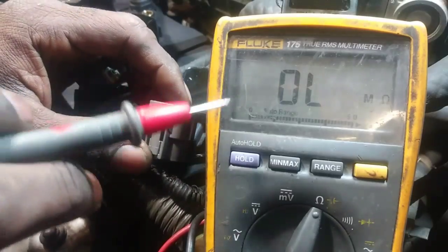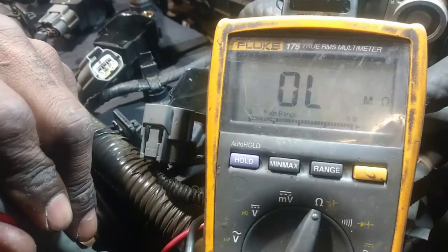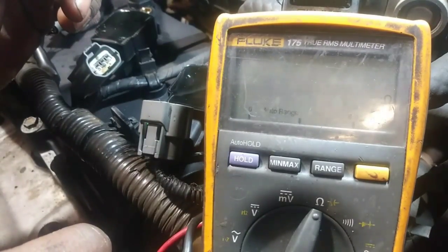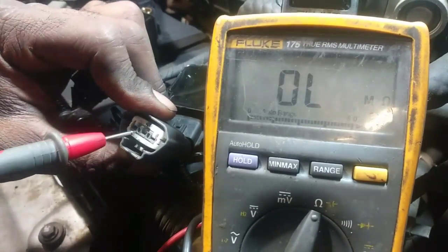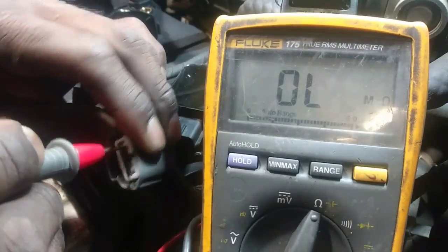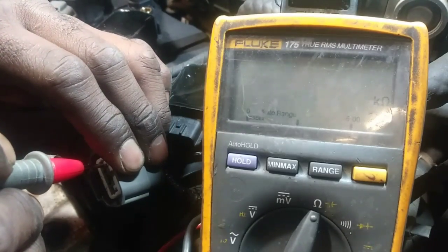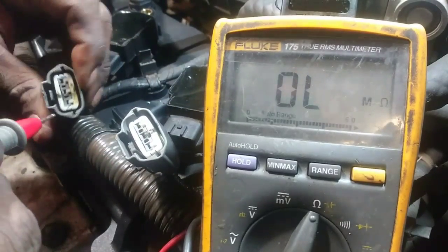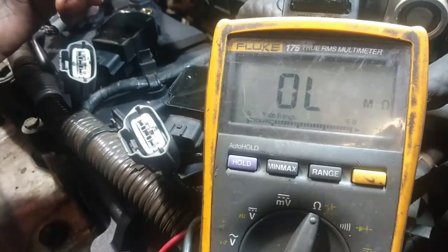Right, so I have my negative side grounded, and I'm going to check the resistance value, which is, there's nothing displaying. All right, so we got, okay, so we got low ohms there. Then I'm just going to check the signaling side of a known good one, see what I have. We have 120 kilo ohms. Let's check the bad one here. It should be pretty low. Yeah, we got 11 ohms on that one.